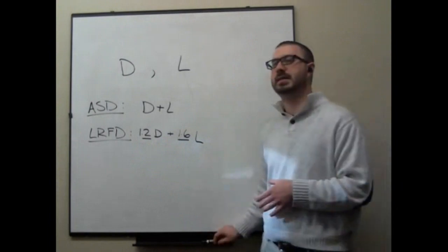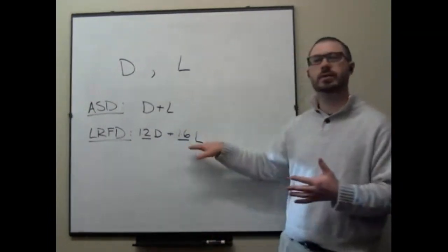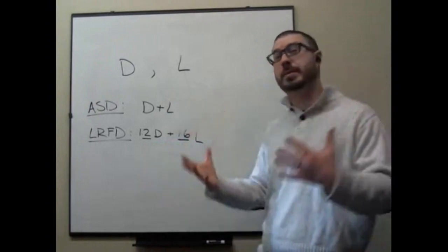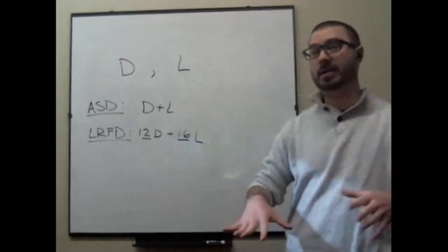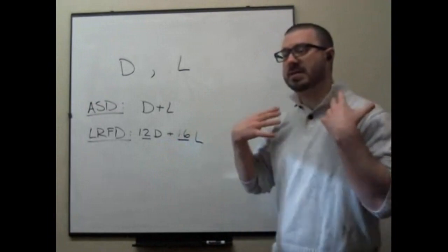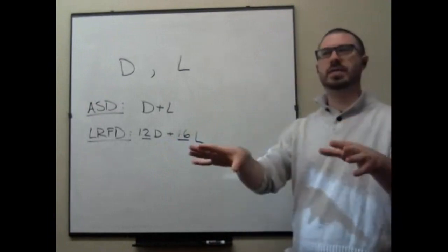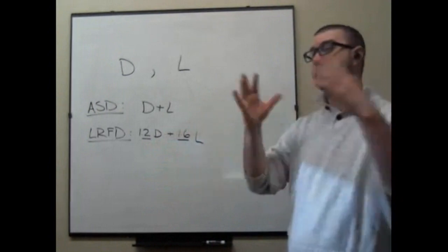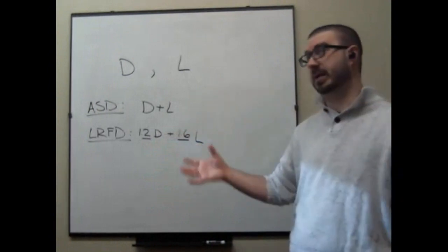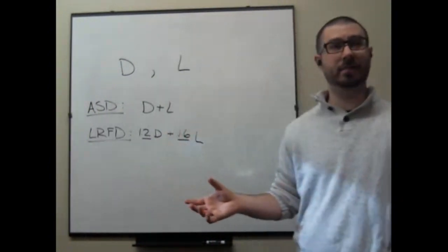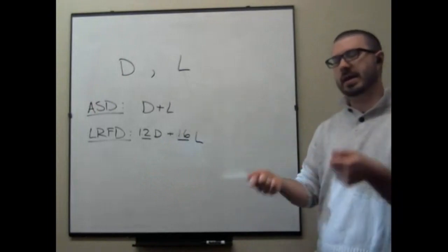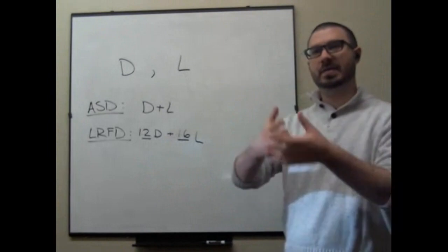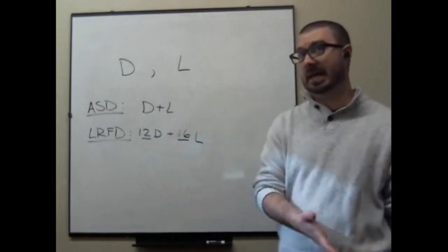Why do we increase the live load more? Like, why is the load factor higher for the live load than it is for the dead load? Well, it all goes back to uncertainty. I don't know about you, but if I was a designer and I didn't know anything about Marshall University, I didn't know anything about the engineering program or anything, and I'm just designing a university building like the Weisberg Applied Engineering Complex, the outsider looking in, I'm going to be more certain and be able to better estimate the dead loads than I am the live loads.